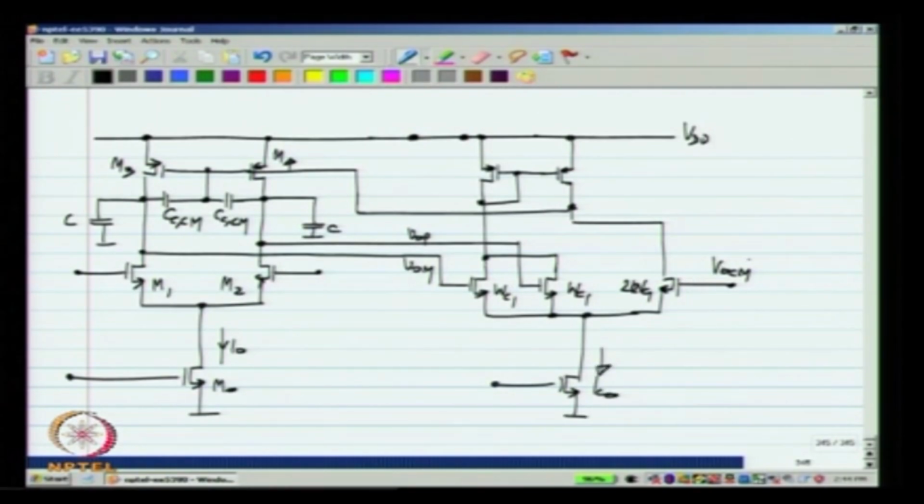Okay. So, this circuit is the same when the op amp is in quiescent condition, when VOP and VOM are equal to VOCM. Now, it turns out that this circuit has some advantages when VOP and VOM are different from VOCM, how the circuit behaves and so on. It is somewhat advantageous to have this circuit with the two sources tied together than the previous one. So, this circuit is also used quite often, okay, and it has the same benefits of not loading the differential op amp. Okay, it does not load the op amp in the differential picture.